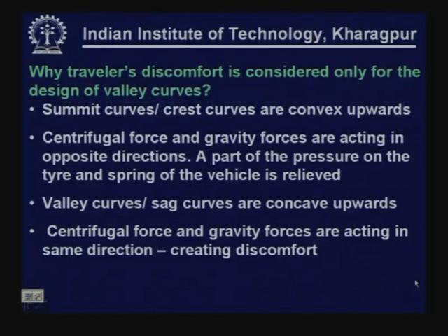Now, why is traveller's discomfort considered only for the design of valley curves? This answer is simple. The centrifugal force and gravity force are acting in the same direction. That is why only for this kind of valley curve it is considered. In summit curve they are acting in opposite directions. So, there is no problem of discomfort. Thank you.